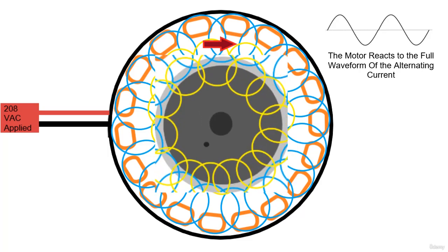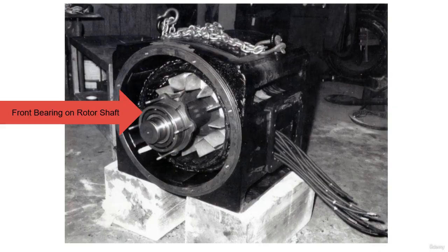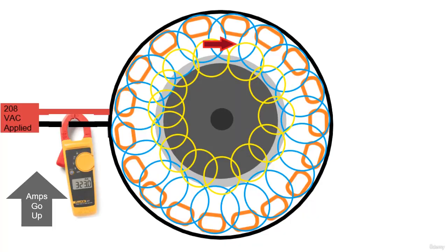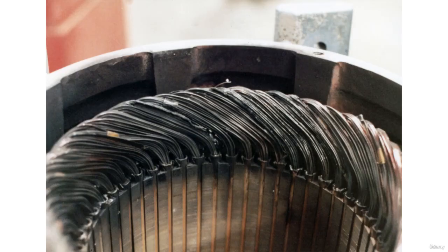If the motor bearings seize up, or the work we are doing slows the shaft or the attached rotor too much, the magnetic reaction changes. The built-in impedance is changed, and we risk burning up the motor windings with high current.